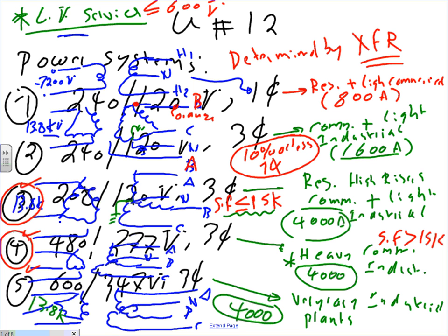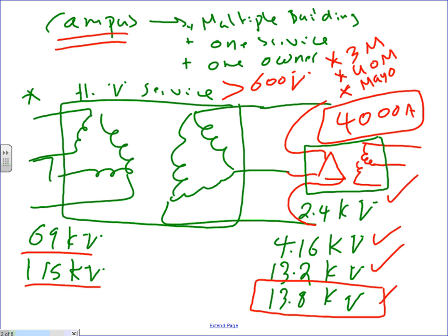Okay, now Ashley, these are low voltage services. How about high voltage services? Can I bring 4160 to Dunwoody and burn the equipment at 4160 volt? Yep, if you justify it. They call them prime service. The second slide, which you have right underneath in the same sheet that I gave you, I want to emphasize the word high voltage services right here, higher than 600 volt. Higher than 600 volts. So buildings like the U of M, 3M, Mayo Clinic, these are multi-campus buildings, guys.